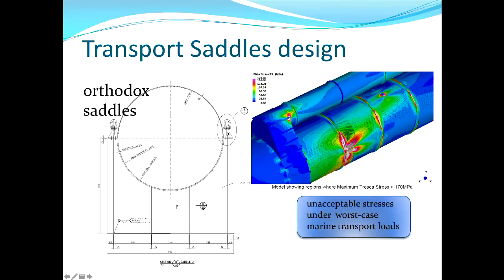There's all this sort of jargon that the pressure vessel industry uses. In that region, and this is a purely standard orthodox design of a saddle. And often if you've got a horizontal vessel for storing petroleum or whatever, it'll sit in standard saddles that look just like that. But for the prill tower, these are just being used for transport. Well, something needed to be done. This was not acceptable. We were going to end up bending the shell of the prill tower beyond its elastic limit. We'd end up with little dents in it, and that's really, really bad. You don't want that.